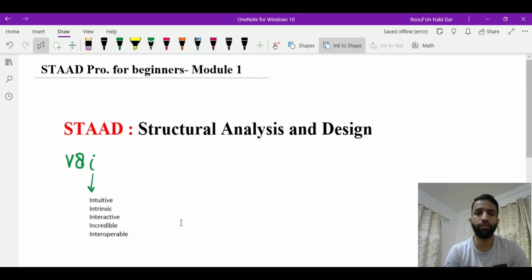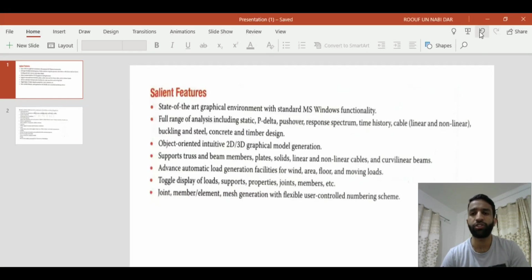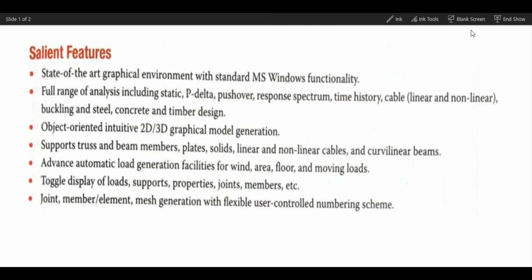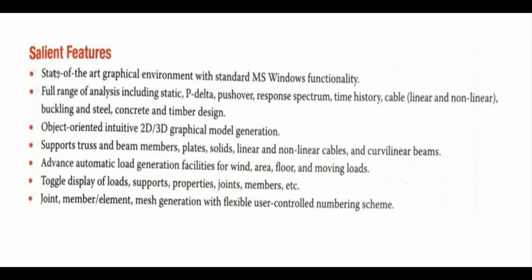So if you look at the salient features of the software, it has the state of the art graphical environment with standard MS Windows functionality. We will be able to do n number of analysis like static, p delta, pushover, response spectrum analysis, time history analysis.